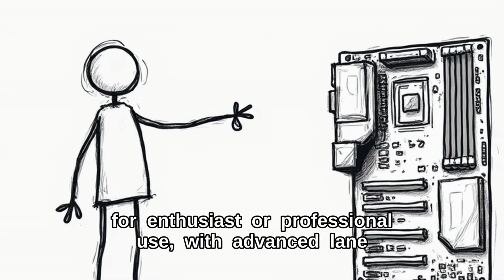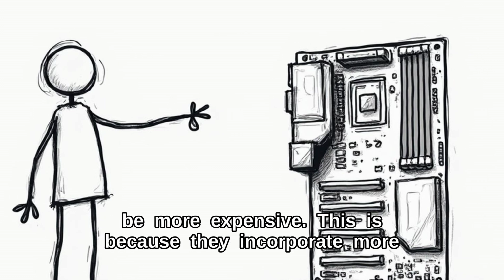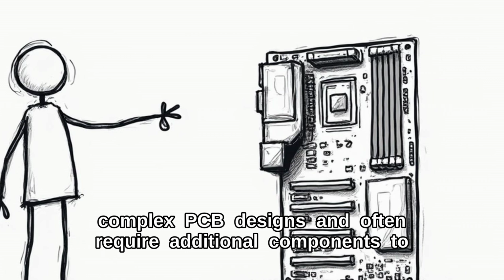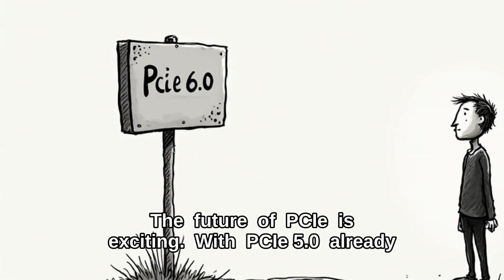Adding to that, the cost of motherboards often scales with their lane management capabilities. Boards designed for enthusiast or professional use, with advanced lane splitting and more direct CPU-connected M.2 slots, tend to be more expensive. This is because they incorporate more complex PCB designs and often require additional components to manage the lane routing effectively.